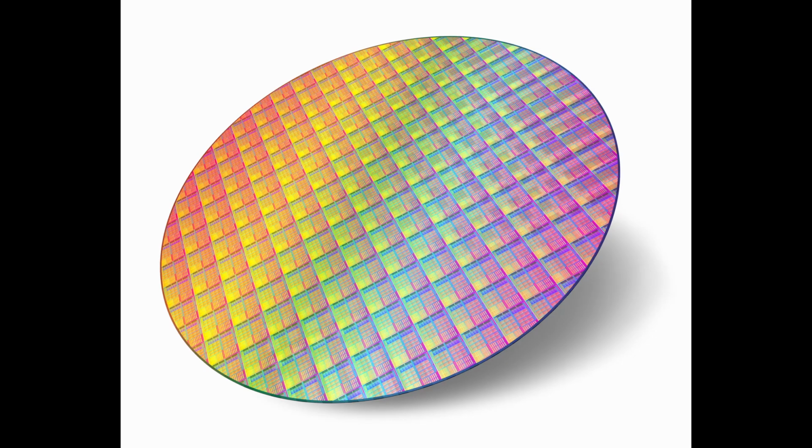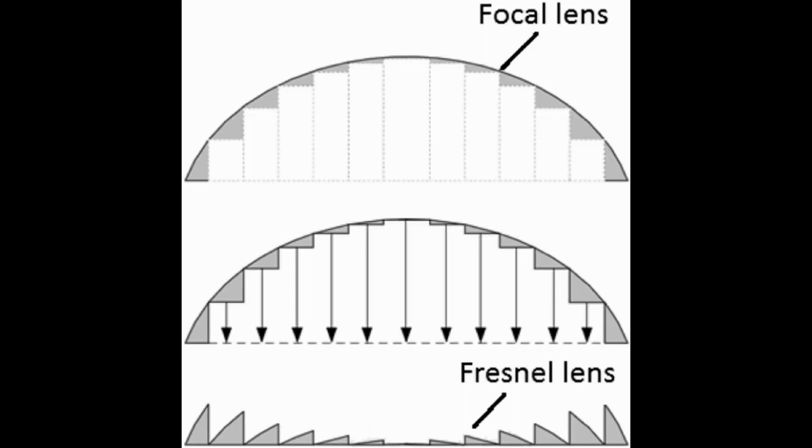Infrared in this range will not pass through many types of materials that pass visible light, such as ordinary window glass and plastic. However, it will pass through, with some attenuation, materials that are opaque to visible light, such as germanium and silicon. An unprocessed silicon wafer makes a good IR window in a weatherproof enclosure for outdoor use. It also provides additional filtering for light in the visible range.